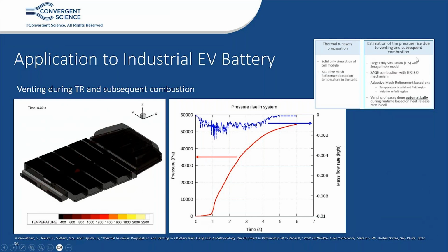For the fluid domain, we made use of high-fidelity LES simulation, and a SAGE combustion model was enabled with the GRI mechanism. And then we can study both the combustion behavior inside the pack, the predictive venting behavior out of the individual cells, and also the pressure buildup inside the pack, which can be evaluated to understand stresses on this particular battery pack frame. This was part of the previous case study I showcased, which was showcased at our CONVERGE user conference.